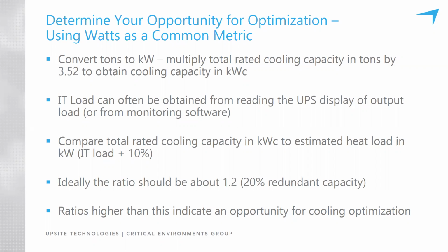And remember, watts is the common metric we're going to use. So it's real easy. Once we get everything converted, now you can compare a watt of cooling to a watt of IT load. Your IT load can be gathered simply by reading the UPS display or an output load from some monitoring software, but you can grab the IT load off the UPS, and that's usually already in kilowatts.